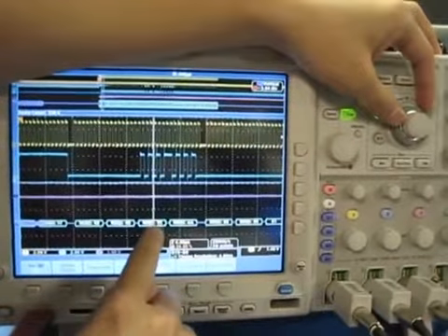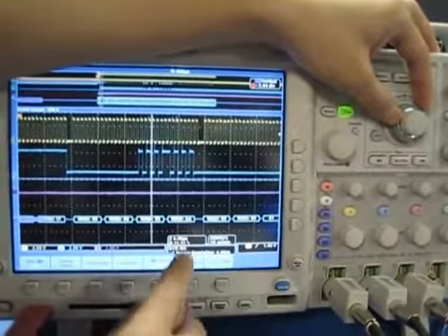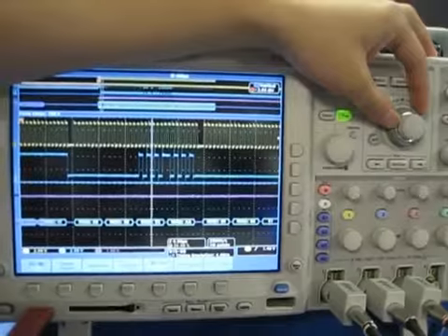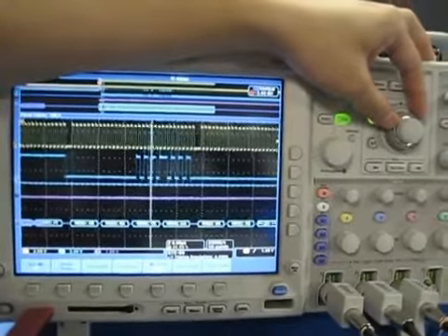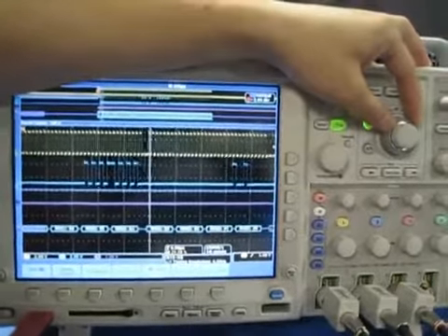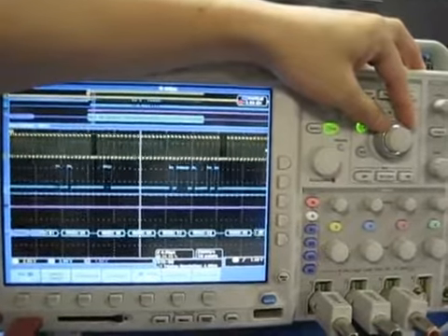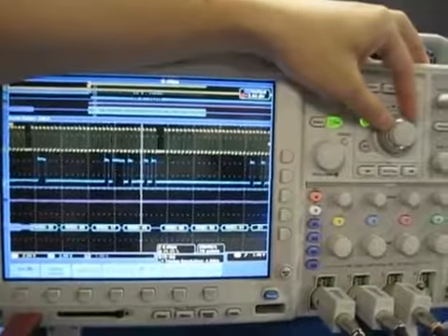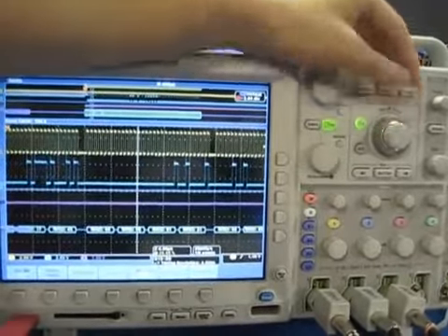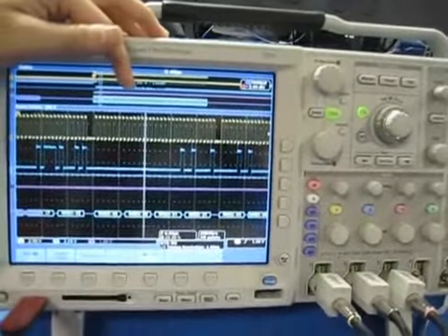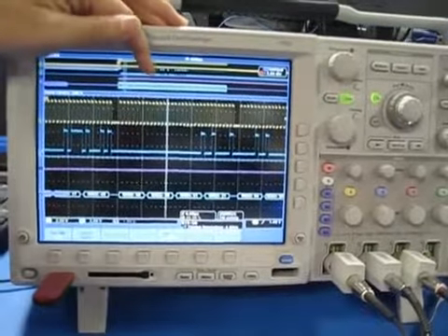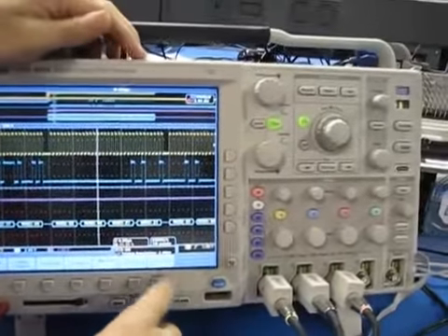see the really valuable tool: we can see all the decoded SPI data, like a protocol analyzer. Once we find 55 and AA, this is the boot initialization code. After that, the chip will initialize the whole internal peripherals and also initialize the memory.